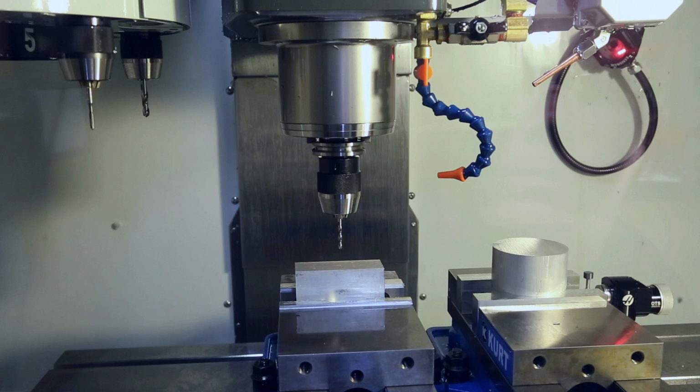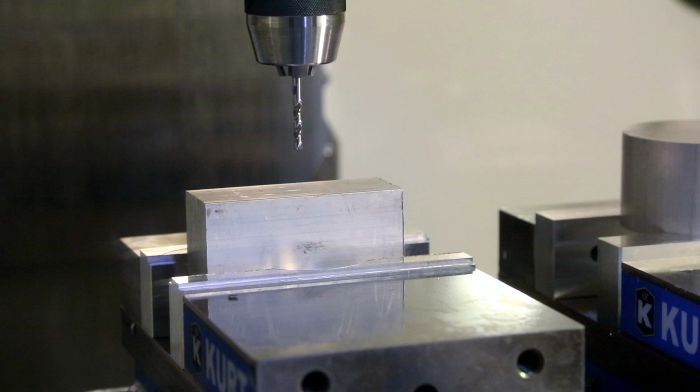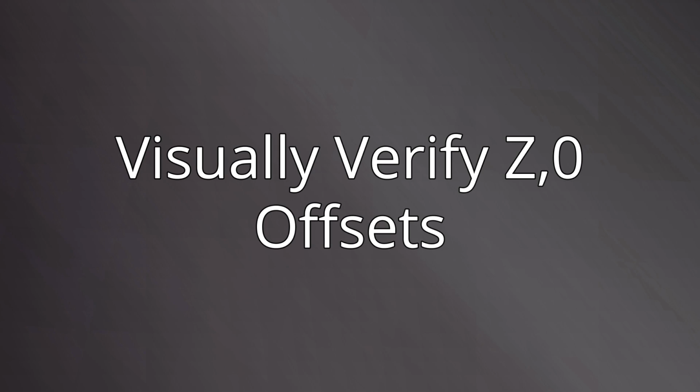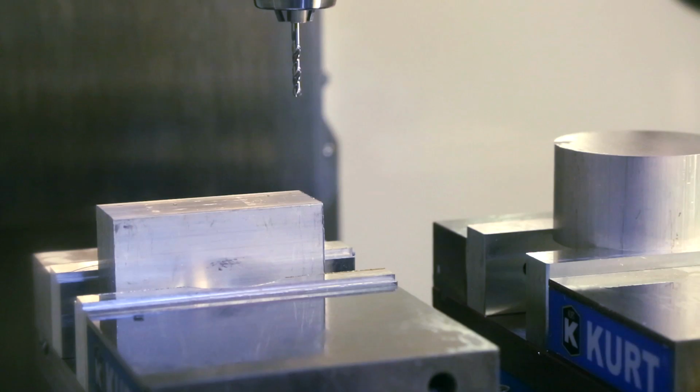Before running that code in MDI, ensure the tool is well above the workpiece. Press Cycle Start. Here's that again from another angle. Now, let's visually verify our Z work offset and tool height offsets in conjunction.